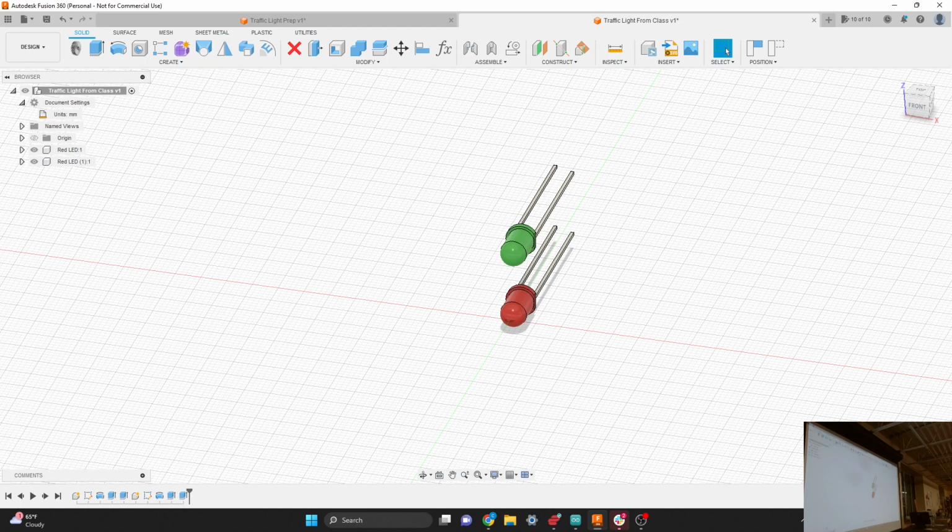And then you can pick the component. So right now you've got object type of bodies that you're moving, so you can change that to components. And then you can choose that component, whichever one, because they kind of exist right on top of each other. Yeah, there you go. Cool. I just moved it up a little bit. We'll want to move it into place after we do the next step.